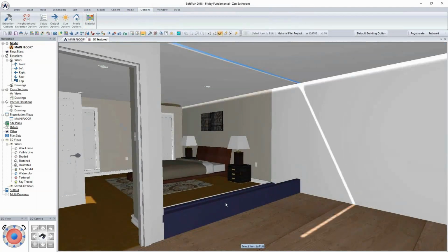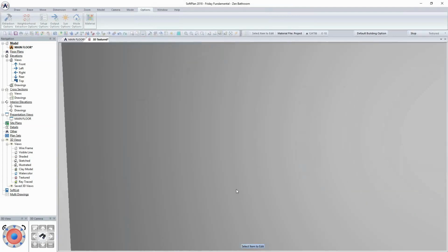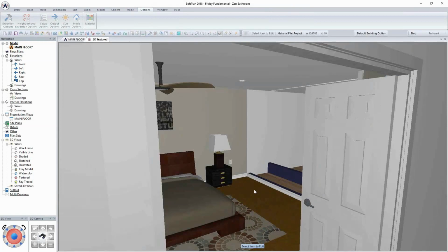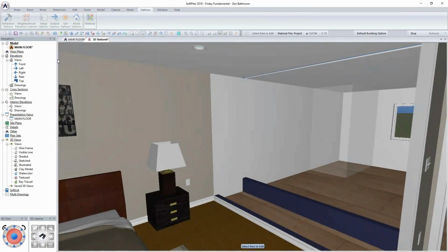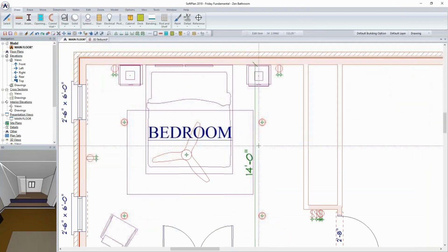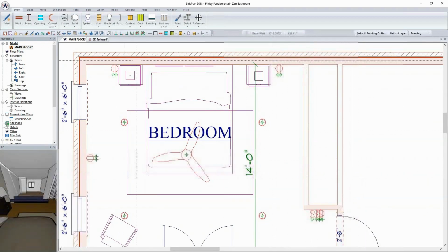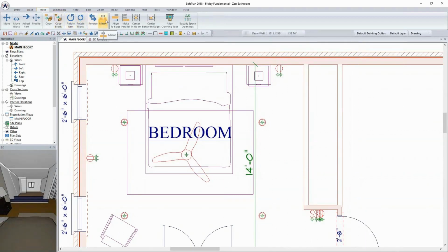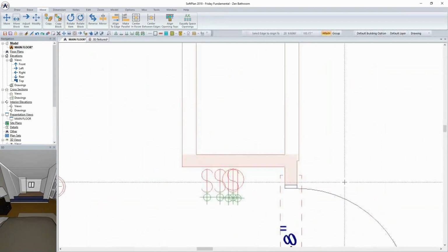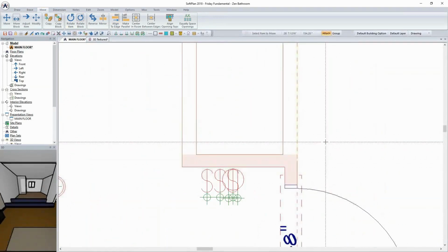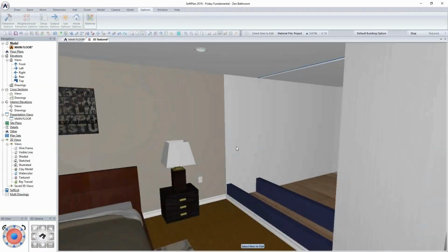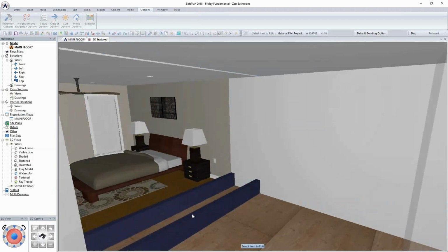Okay, and so now we've actually got this shallow curb wall that's going to be in there where I can create kind of a see-through area. I'm just setting this all up here on the plan right now, and so I'm going to do the same thing here. I'll just pick draw select, and I'm going to draw this same wall in here like so. Now, using my move and my align to edge, I'll be able to come in, select this edge of the wall and just align those two. And so we actually have kind of our curb right here.